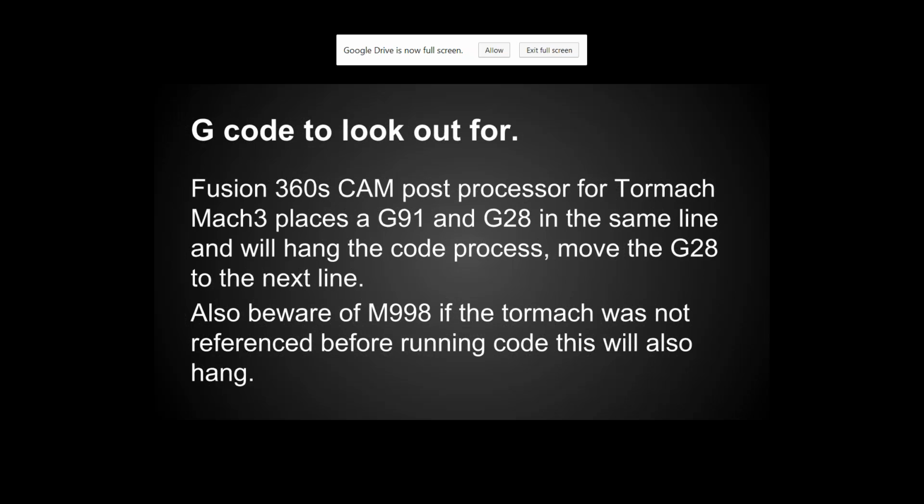If you have to have 3 different drill bits for drilling a hole in a 1/4 plate, it might be just easier to throw the end mill that you're going to be using for your final chamfer mill in there and just use that to bore a pocket out versus drill it out. The minimum amount of tool changes you can get is probably the best for the Tormach.